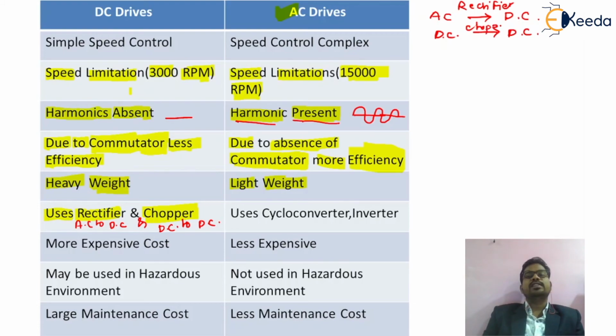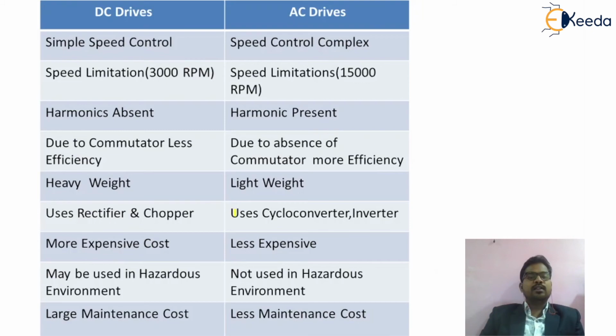So these different power modulators are required for the DC drives as well as the AC drives. After that, the AC drive uses different types of power modulators, called a cycloconverter and inverter. In concern with the cycloconverter, we have a change in frequency, meaning we have an AC supply and our motor is an AC motor, then we obviously use a cycloconverter or regulator for that particular application.